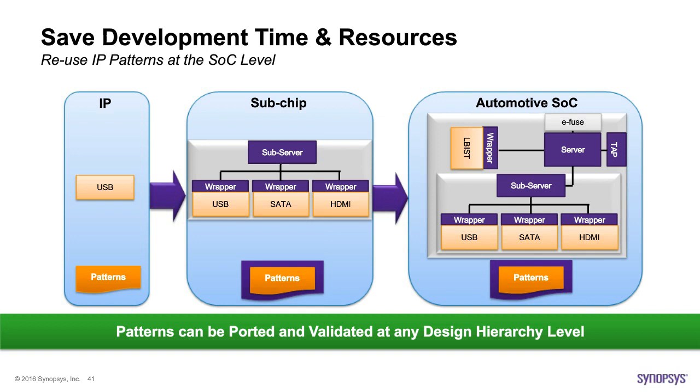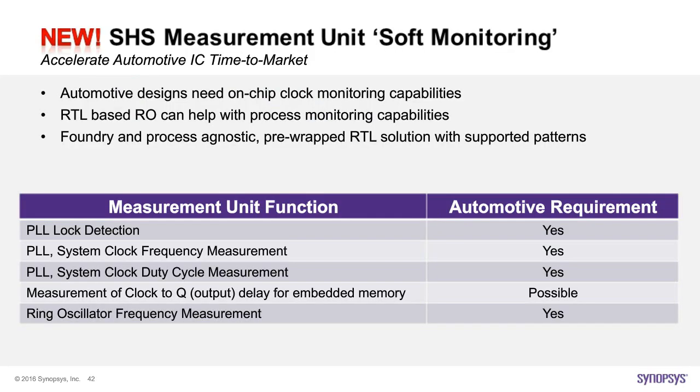For manufacturing tests, the reporting is done typically through the TAP controller. For non-manufacturing tests in the field, whether it's power on or mission, the reporting is done through the internal processing engines inside the SoC. And for all of this to happen, we need an extra level of sensors to be built inside the chip. Again, the star hierarchical system that we have created for such purposes does come with numerous types of engines that help us sense and measure the different signals. Whether it's timing oriented, that is performance, or process oriented, it will give us the possibility to sense and to transfer that information as we move forward.